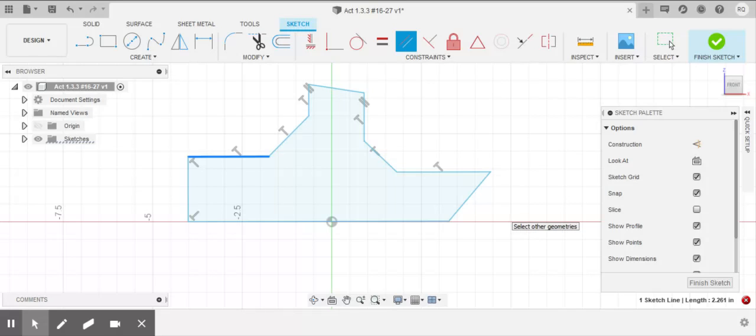It says to make a sketch of what you've got, that little boat there, and all the constraints that you added. Remember, we made this perpendicular to that one. Okay, we tried to make this one parallel with here, but I think it didn't allow us to because it was over constrained. Okay, next. All right, welcome back. Next, for 22, it says to use a construction line to create a vertical line through the midpoints of lines 1 and 6. We'll later use this construction line as a line of symmetry.